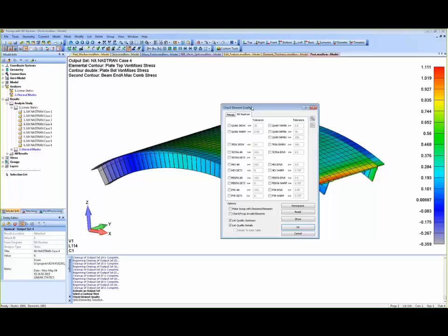These checks are probably similar to the other versions of Nastran, however these checks do correlate directly with NX Nastran specifically. So all of those geom check options from NX Nastran are now included here. And again, this will save you time before you hit the analyze or the run button, so you can ensure that there won't be any geometry errors.